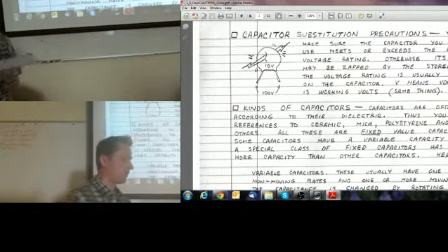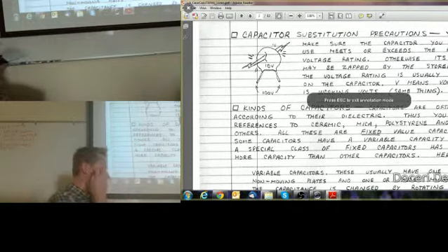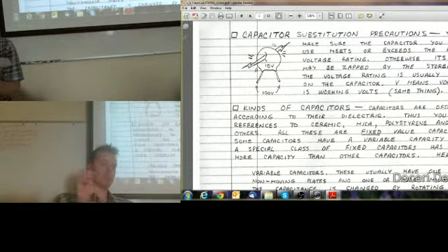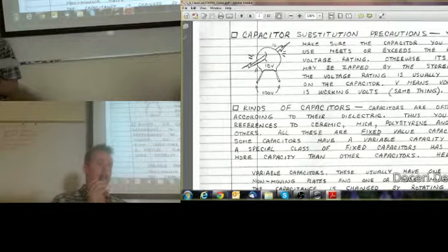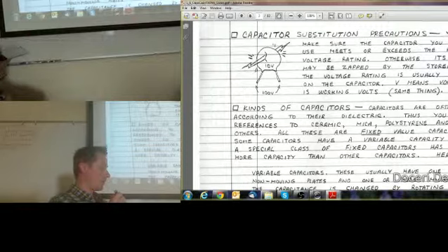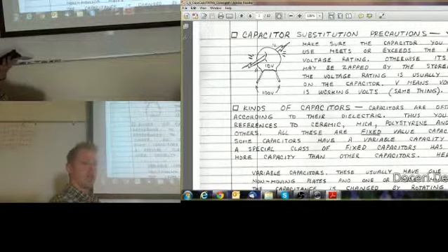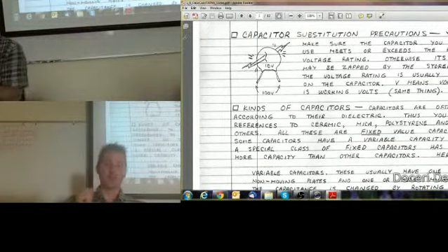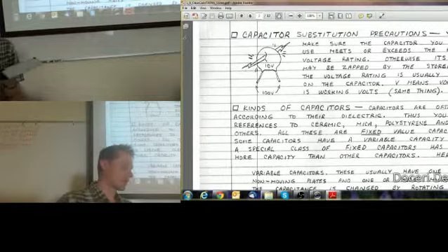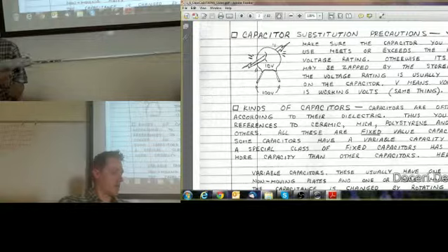But now, with that said, you always want to make sure that you meet the voltage requirements of a capacitor. For example, the electrolytic capacitors over there are marked with a voltage. Some of them are 10 volts, most of them are 50. If you have a 10 volt capacitor and you put it on up to 20, it could zap that, or it could pop the top of it off. Those electrolytics look like confetti when you put a voltage across them that's higher than the rating for that capacitor.